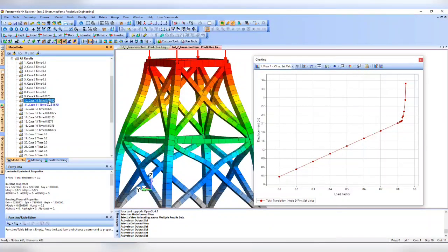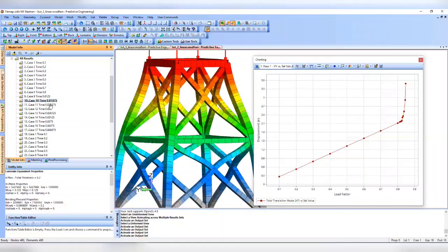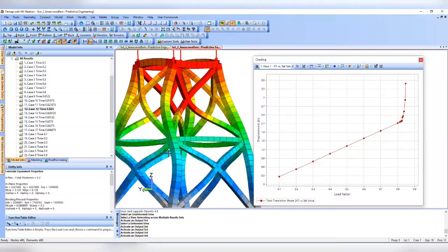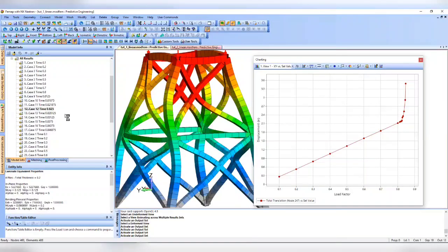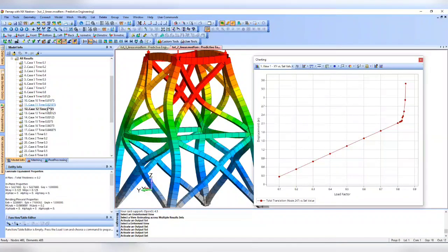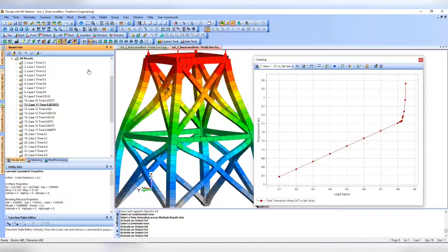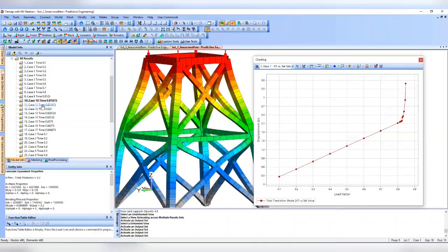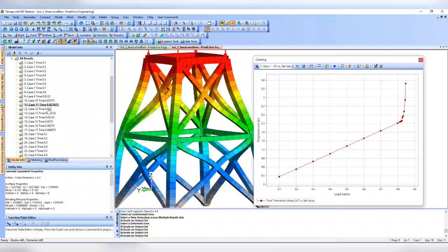The total load that I applied was 100 pounds. It's telling you that it's going to fail at around 80, 81, 82 pounds before it gives out. So the linear solution is giving us a value of 0.8. And this nonlinear solution, where you go in load increments, is pretty close, right? It's not too far off base. It's 0.82, so it's a little bit different. You would expect some differences because it's not running the same type of solution, but this linear eigenvalue solution is giving you a very good first basis run. And if you want to fine tune your analysis, you can run nonlinear and get more fine tuned results.